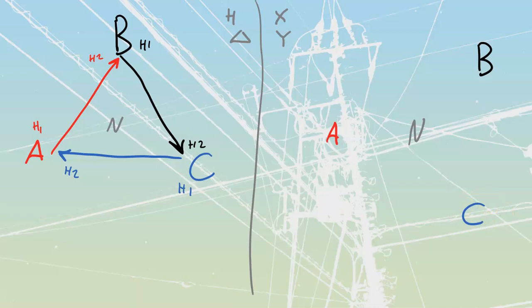Then we're going to go back to our high voltage side, and now we're going to draw in our low voltage windings. Our low voltage windings are always in parallel with our high voltage windings, or at least the phasors are, I should say. So we draw them in, tails and heads over there. So now that we've got those laid out, the next thing for us to do is transfer those low voltage windings over to our other side.